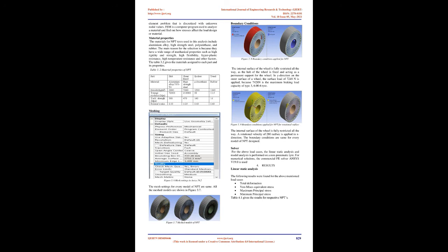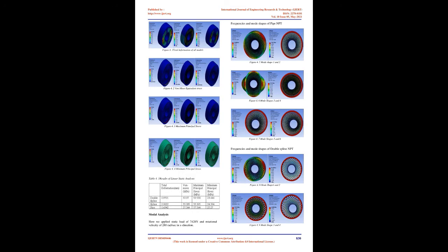3. Methodology. CAD model. The measurements of the tire of the Cessna 172 aircraft are obtained from the Goodyear Aviation Company Tire Data Book. The aircraft's tires are classified into types. Most of the aircraft's tires are of Type 3. The type of tire being used for the Cessna 172 is referred to as 6.00-26, where its geometric data is given below. The NPT is classified into types depending on the number of layers of structural spokes. There is single layer and multi-layered.